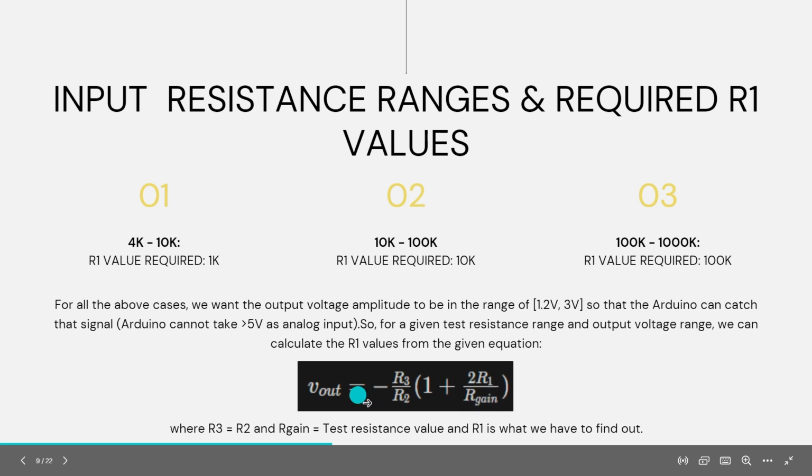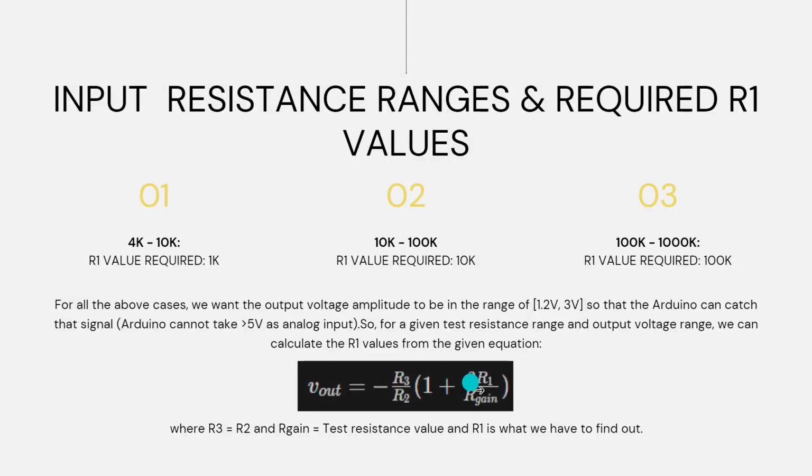Now we chose V input equal to 1 because we want to show the result using Arduino. Arduino can measure from 0 to 5 volts, so we want to take the range from 0 to 5. That's why we gave 1 as an input voltage, because a small value just greater than 0 would also work, but the problem is that Arduino can't measure above 5. That's why we took the voltage 1 as an input.